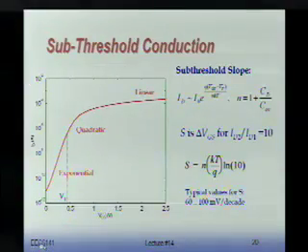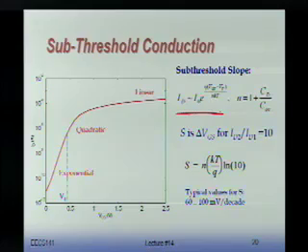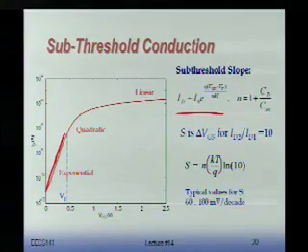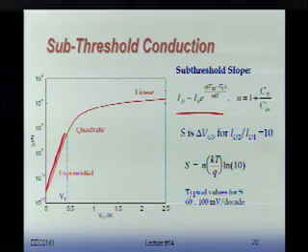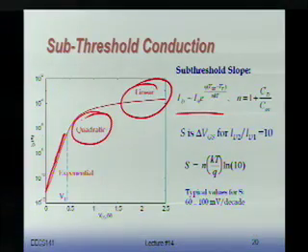If you're a curious person, here are the equations for it. Actually, they're very similar to the bipolar equations. The current in the subthreshold region is, as you can see, in superthreshold, you have linear behavior, this velocity-saturated device. You get closer to the threshold, you get more quadratic. And then you go subthreshold, you get an exponential dependency. Okay? And the equation is like the bipolar equation.